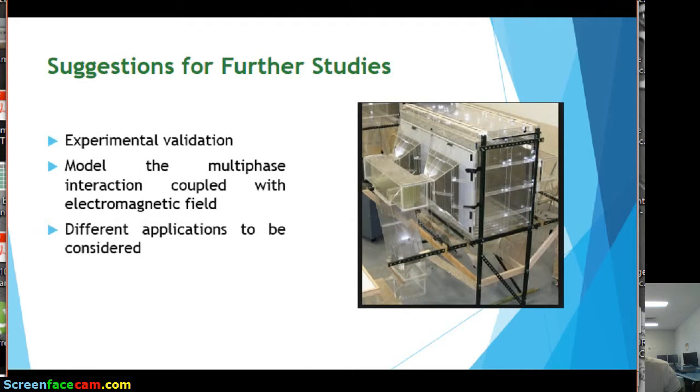Now, at this stage, it must be added that in order to assess the effectiveness of the optimized geometries, the incorporation of secondary phases is required. Nonetheless, assuming that a high applied voltage and large particles were considered, the geometries highlighted are considered optimal for dust collection. Now, our model developed good predictions of flow distribution inside the electrostatic precipitator. Those results are then encouraged to be applied and compared with results obtained in a laboratory scale electrostatic precipitator.